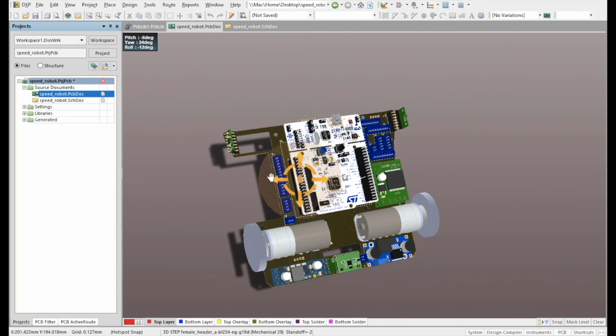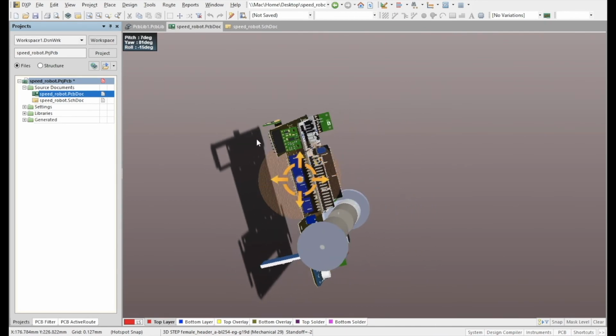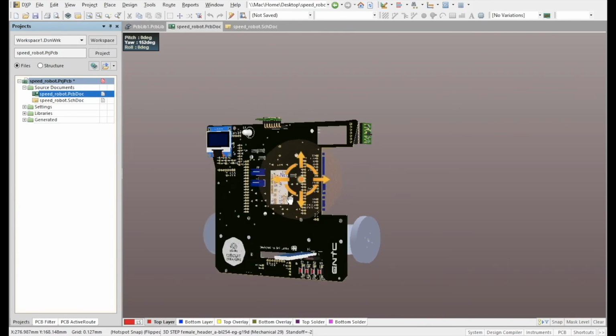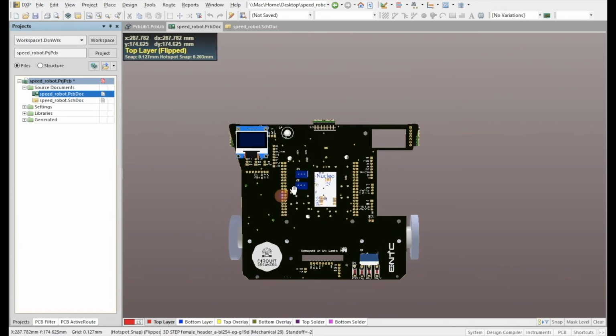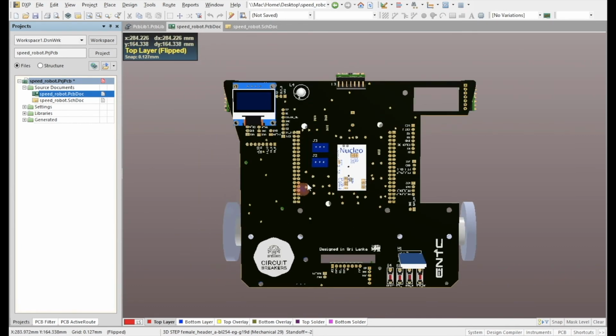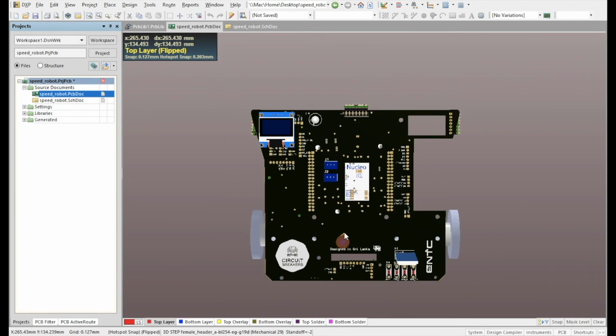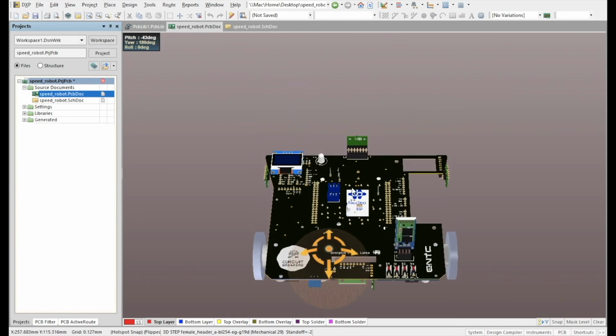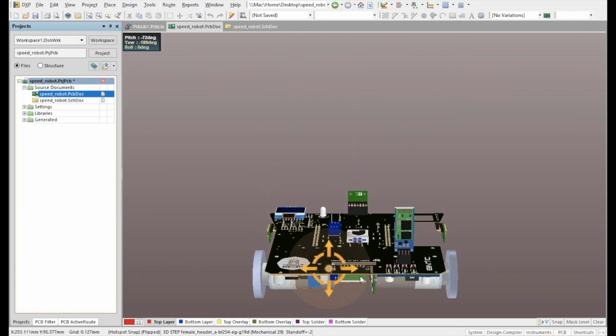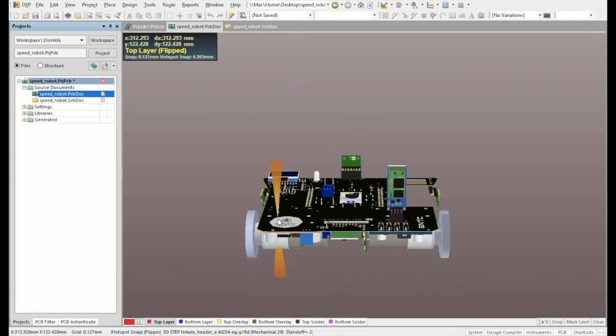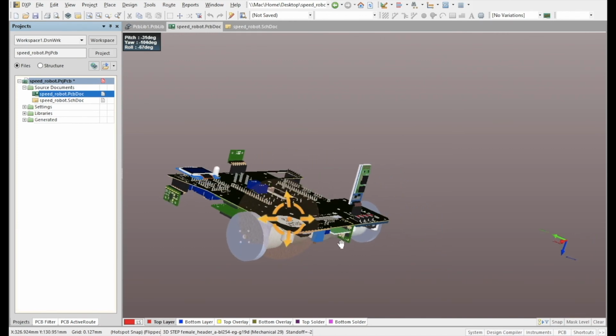But we faced one issue at the first stage, as there was a connection between the PCB's ground net and the external cover of the metal gear motor. This issue occurred because we mistakenly put the copper very close to the nut holes of the PCB. A small scratch made by a nut was the reason for the connection between the motor and the ground net of the PCB.